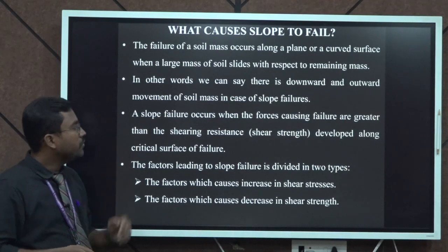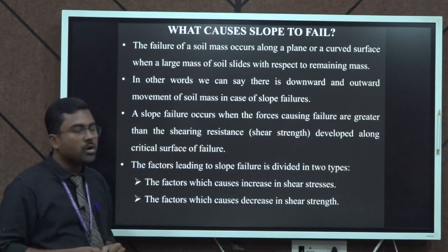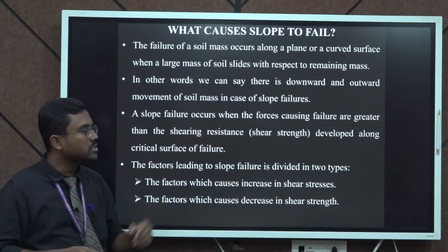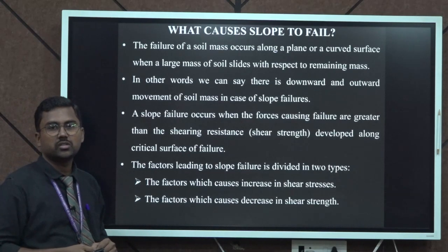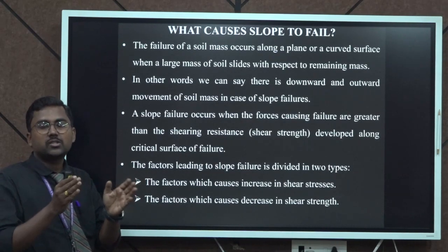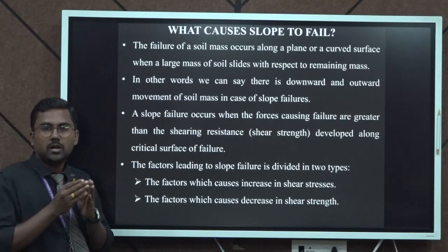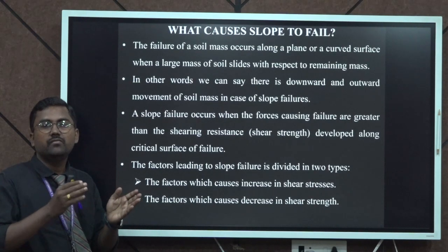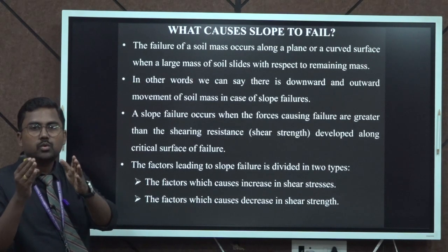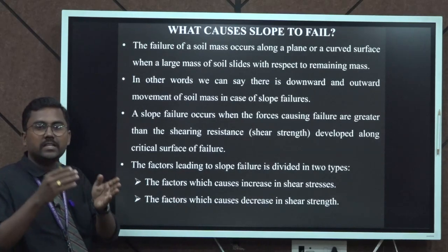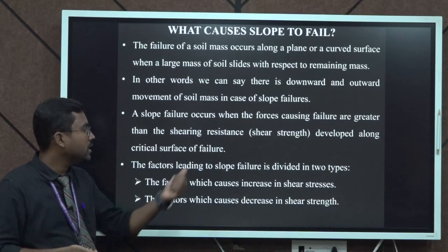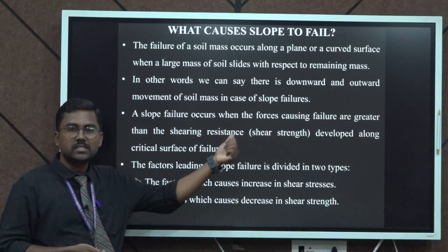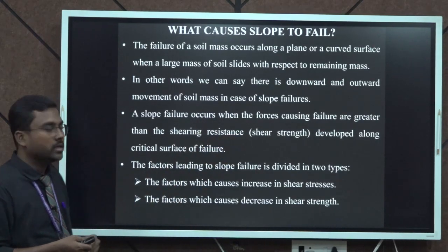Also, the failure occurs when the force causing the failure is greater than the shearing resistance, the shear strength of the soil. That is, the soil naturally has a shear strength capacity that will resist the failure of the slope to some extent. If the external load acting on that slope exceeds the existing shear strength of the soil, the slope will fail.